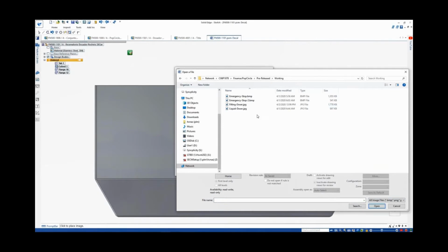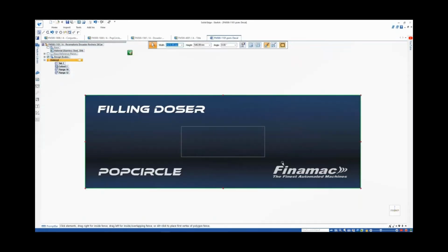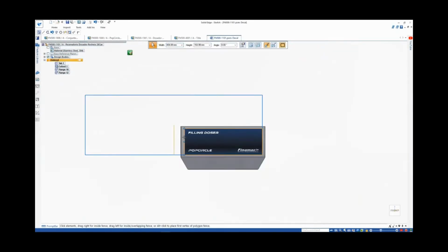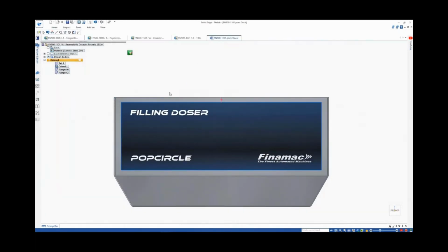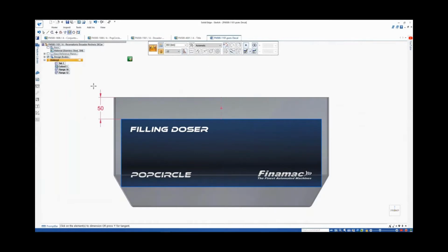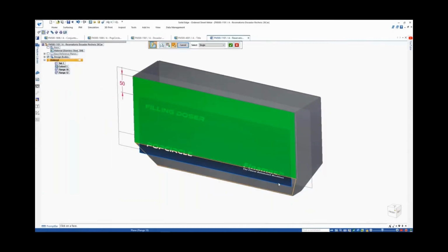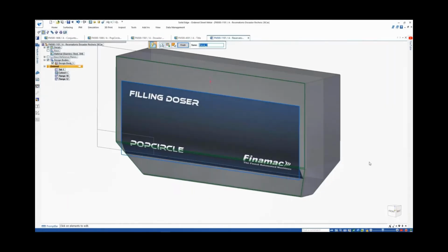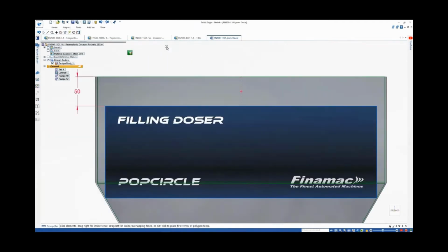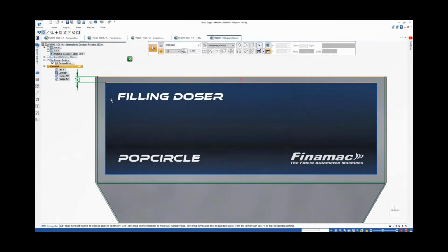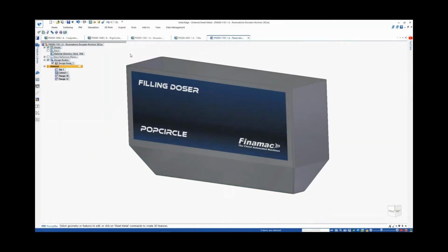There's another neat thing that we have, and that is a decal command. We've got this cool part. Well, now we want to put our company's name on there. You'll notice that adding a decal just couldn't be any easier. We're simply putting it on a surface, then putting a sketch to size everything up, and getting that just like the way that we would want it.